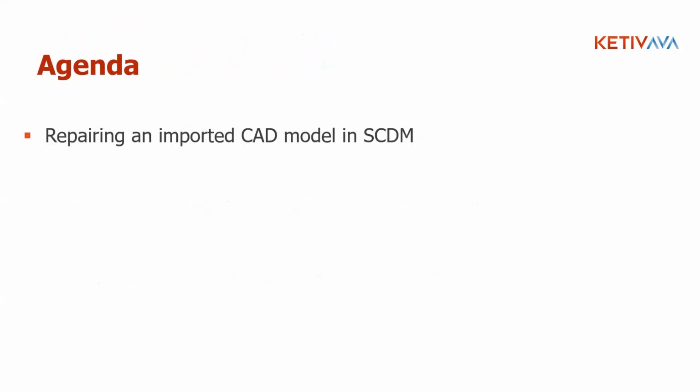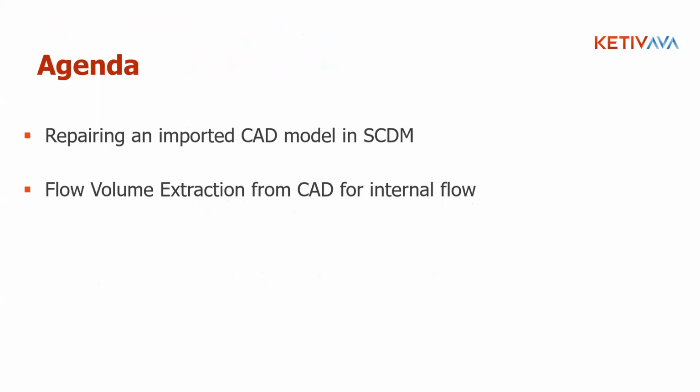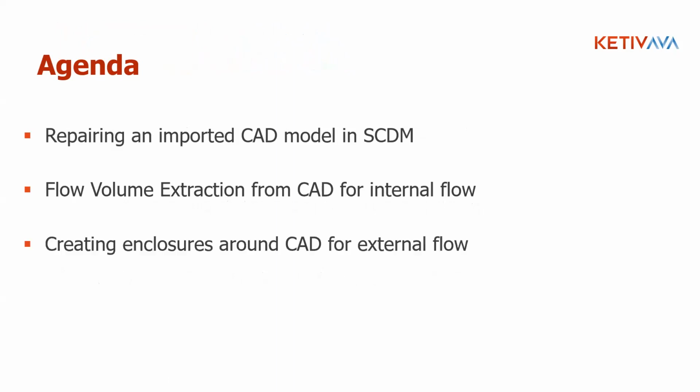So let's start with the demonstration and talk about today's agenda. The first thing that we will be covering is repairing an imported CAD model in SpaceClaim Direct Modeler. The second thing is the flow volume extraction from this CAD for internal flow. And the third part will be creating enclosures around the CAD for external flow.